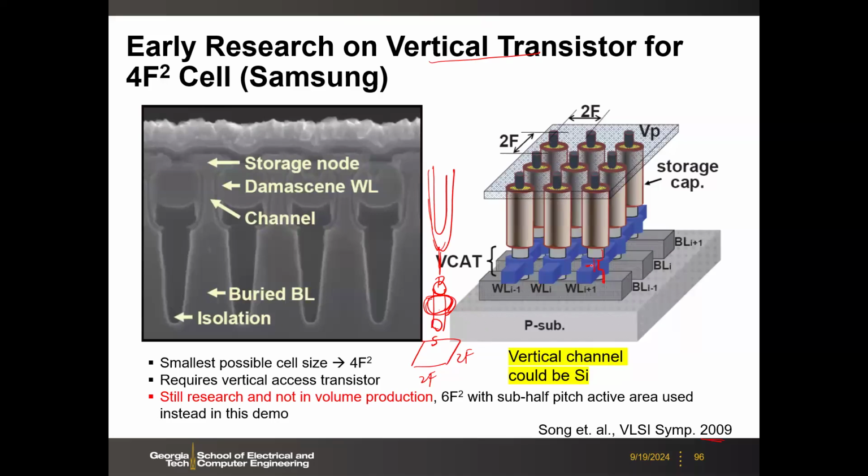So here you see that the VLAN is controlling all the gates. You have those vertical transistor gates, and then the Bitline here is collecting all the sources together. From the top view, you will only have one VLAN wire this way and one Bitline wire this way. And we discussed before, each wire needs 2F: 1F for the wire, 1F for the spacing. So it's 2F by 2F, you get 4F square. Okay.